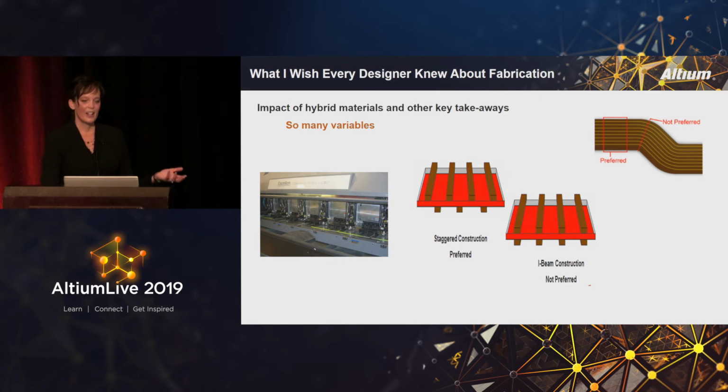And then somebody passed along the impact of hybrid materials. So let's take a complex rigid flex that's using specialized material, maybe ceramic-filled materials. Those materials, as with flex, have a lot of issues with movement. So flex on its own is very hygroscopic. It's going to absorb moisture.